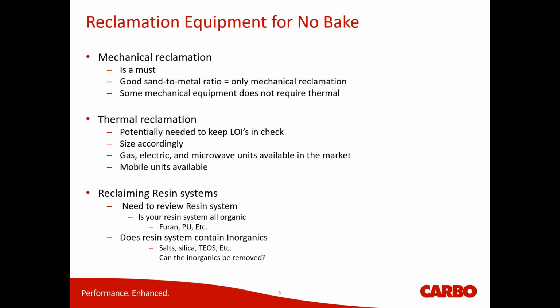As for the salts, what we've seen is we have people that have been running ester-cured phenolic urethane. Ester-cured phenolic urethane is primarily used to prevent veining in silica. Again, with ceramic media, you don't need something to prevent veining, as you don't have veining. The other problem with using that ester-cured phenolic urethane is that it contains a salt, usually sodium or potassium. That salt builds up over time and affects your tensils. Basically, your tensils start to drop out because you've adjusted the pH or whatever of your system.